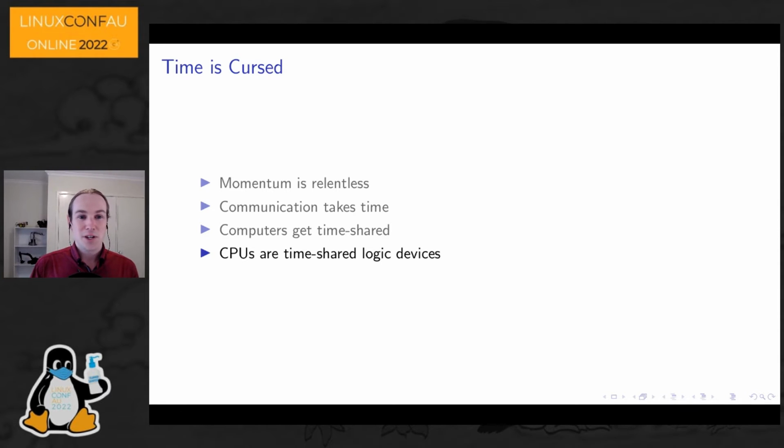The other constraint you can relax is the assumption that we have fewer CPUs than things we want to do. More hardware, less sharing of resources. More CPUs servicing fewer interrupts each, simpler CPUs that have more deterministic timing, or even specialized devices that can implement desired behavior without CPU intervention. A lot of embedded systems engineering for battery-powered devices boils down to corralling microcontroller peripherals to do all of the things while the CPU takes a nap.